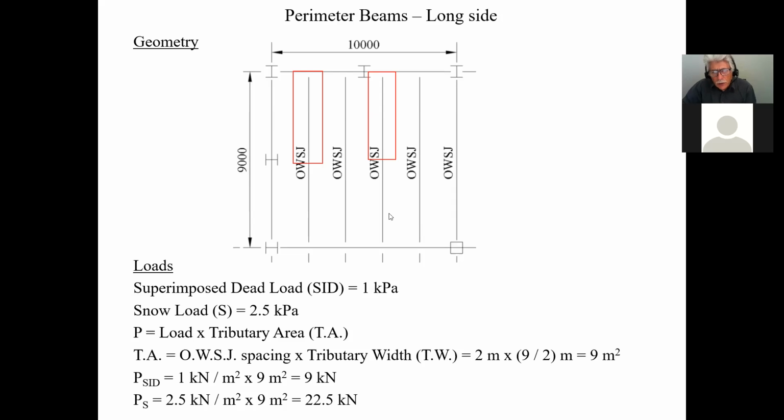Okay. The reason here, when we did the Gerber girder, is that I'm going to use those values to design this column here, and therefore that's why I also put it here at the reaction area, because I wanted to make sure that it included the force for my column design. But here I really don't care, and therefore I'm only applying the ones that are going to be affecting the beams.